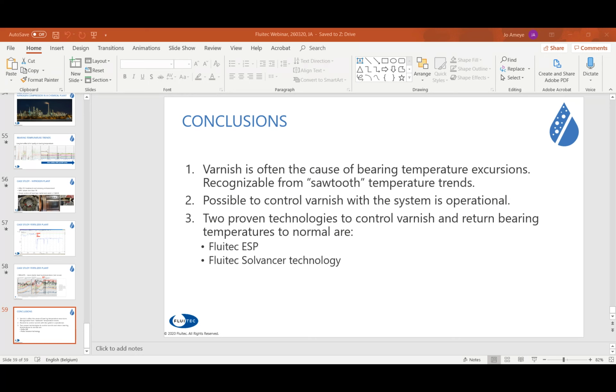Mostly it's found on steam turbines, all types of steam turbines, where you have water accumulation reacting with the additives. Even some bacteria can form into the sludge. It's also a clearly different color. Sludge never really has that orange-brown color. Varnish is a different layer, more attached to the metal surface, while sludge is really an agglomeration. Very, very different, I would say.